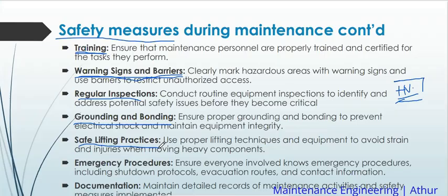When we are doing maintenance, we lift poles. Sometimes we lift poles, we lift transformers. The transformer is very heavy. You have seen in mountainous hills, I remember one time we carried a transformer where they were constructing a mast, and we had to carry it like 50 people. So if you don't take some precautions when they are lifting and those people are singing their songs, you may end up getting injured. So you need to take caution about that.